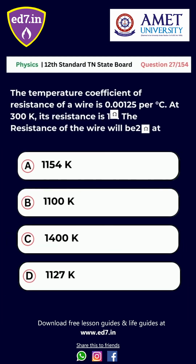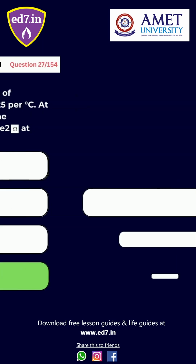Question number 27. The temperature coefficient of resistance of a wire is 0.00125 per degree Celsius. At 300 K, its resistance is 1 ohm. The resistance of the wire will be 2 ohm at option A 1154 K, option B 1100 K, option C 1400 K, option D 1127 K. The right answer is option D, 1127 K.